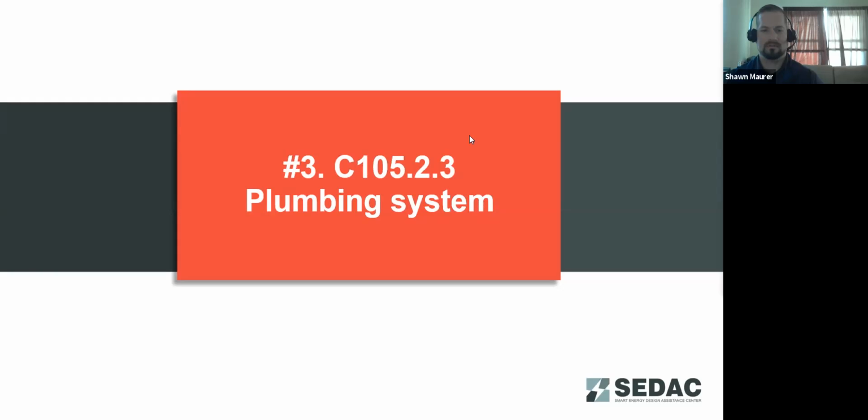Okay, we'll share those results. Can sheet insulation installed with Z channels be considered continuous insulation? This was a little bit of a tricky one. In order to meet the definition of continuous insulation, it can only be bridged by service openings and fasteners. A Z channel would actually create a second cavity, so that would no longer be continuous insulation.